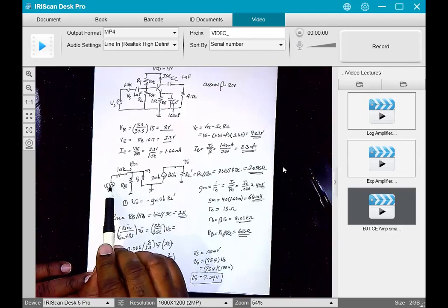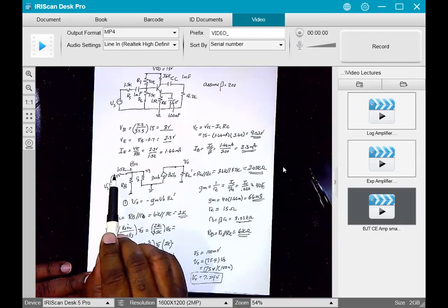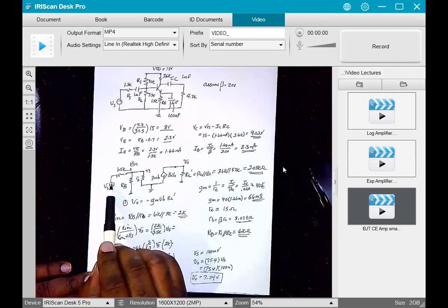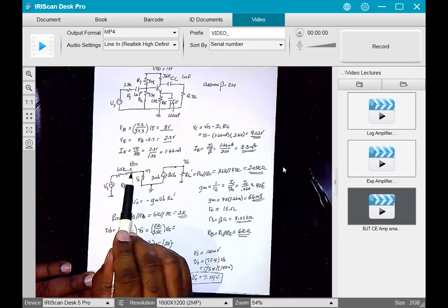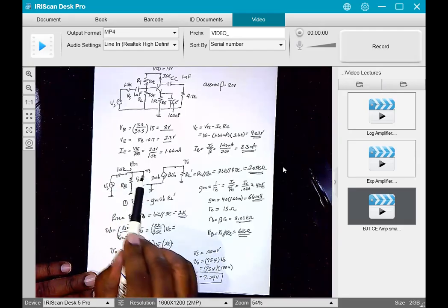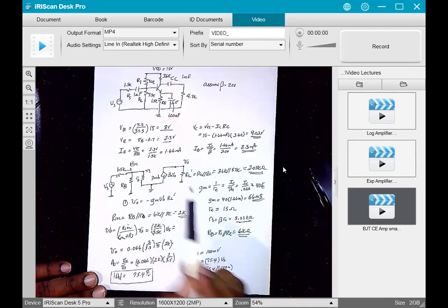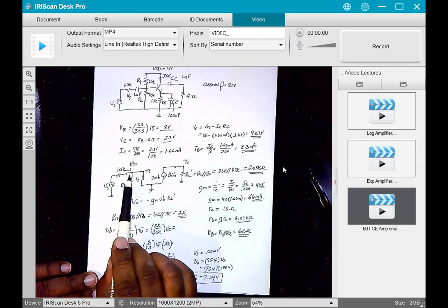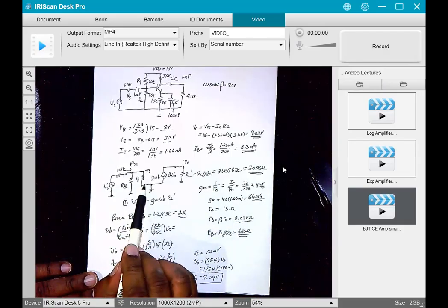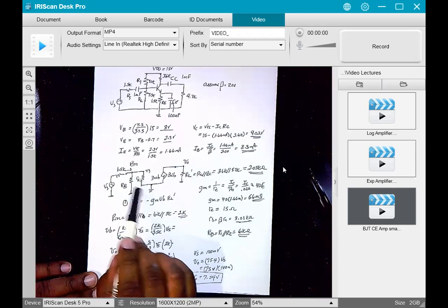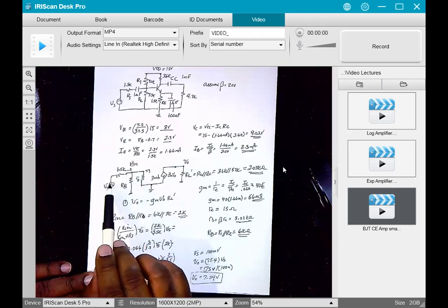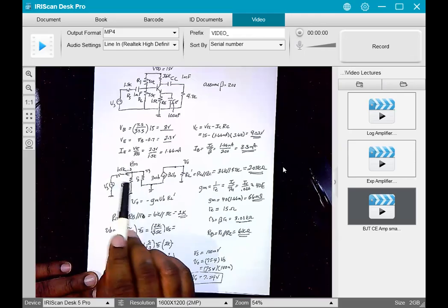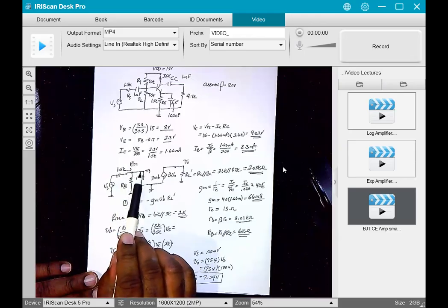If I put 100 millivolts in here, and this was 0, or really close to 0, say 50 or 100 ohms, then most of this 100 millivolts will show up directly on the input here and get multiplied to show up at the output. But because this 1.5K is of the same order of RN, I have a voltage division here. So I may have 100 millivolts here. I may only get 60 millivolts showing up here on the input.